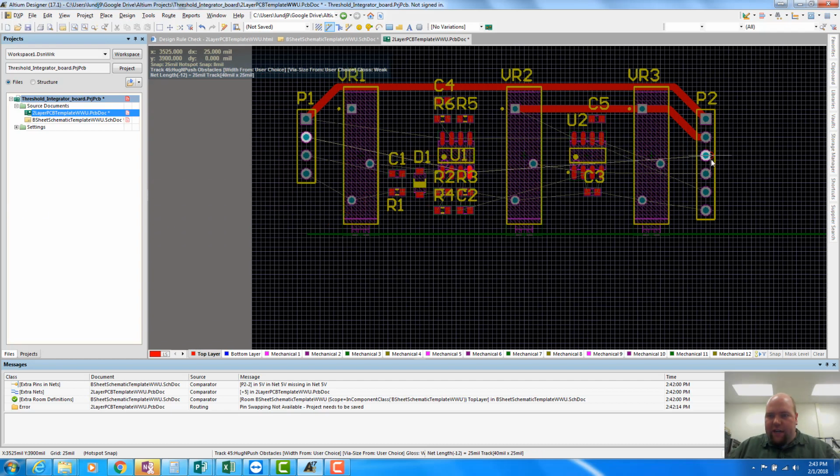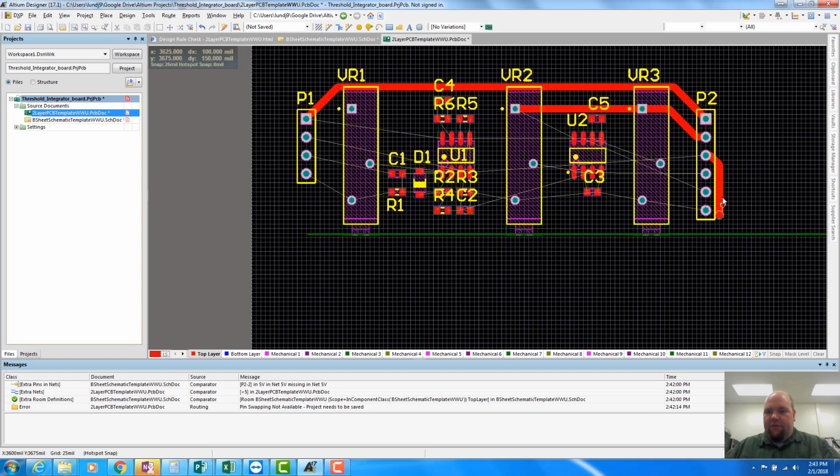This one's a little bit more dicey. I might actually route this guy around the back. Now, we generally want to be careful when routing like this, because in the end we want to make sure we have a ground plane that's fairly close to here. Definitely want to maintain a close ground plane. Actually, this is probably a good candidate for routing on the other side, in fact.